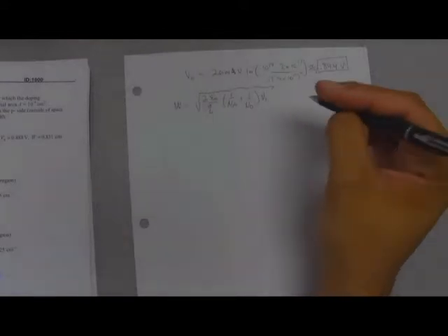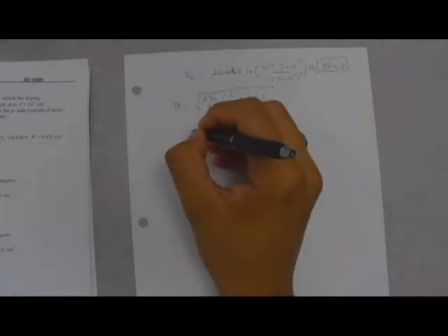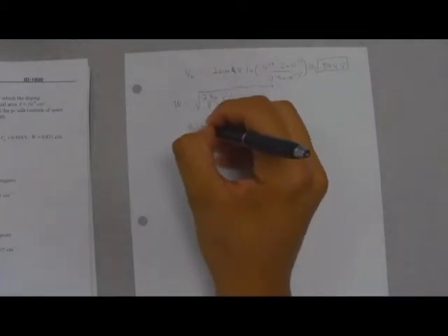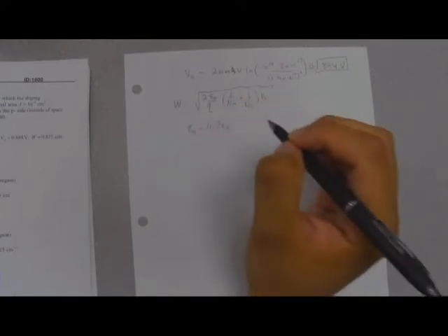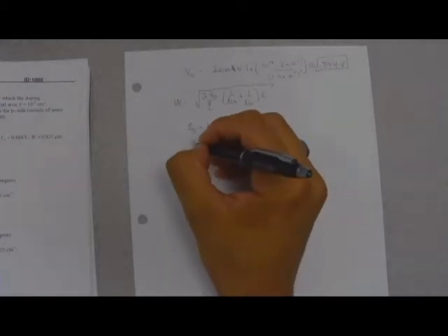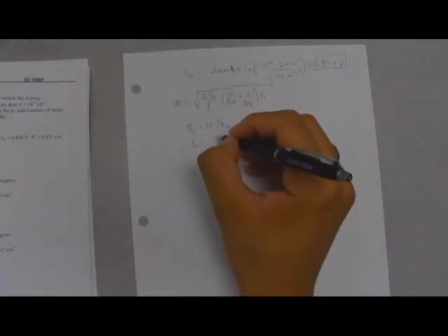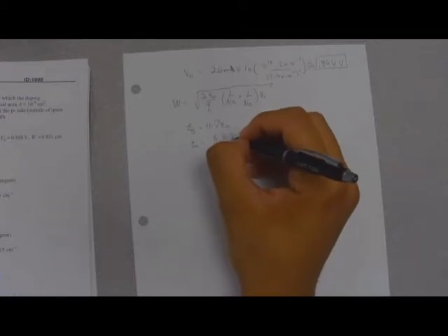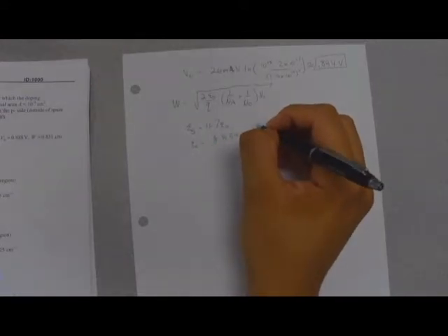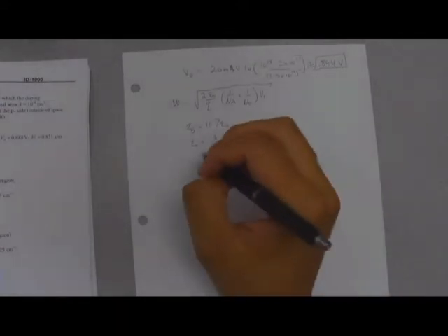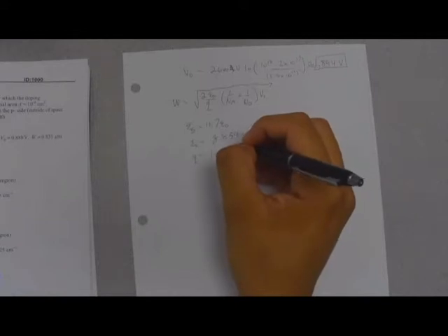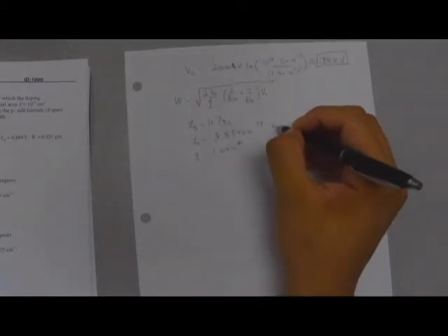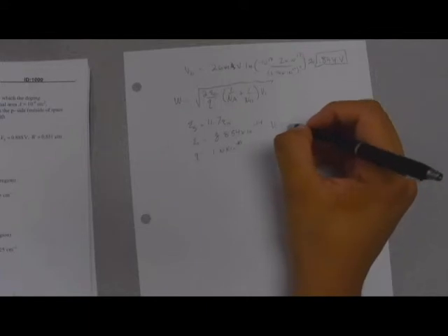So we're given that epsilon s is equal to 11.7 times epsilon naught, with epsilon naught being 8.854 times 10 to the negative 14th. Q is Coulomb's charge, 1.6 times 10 to the negative 19. And that V naught is the V naught we calculated earlier as 0.894 volts.